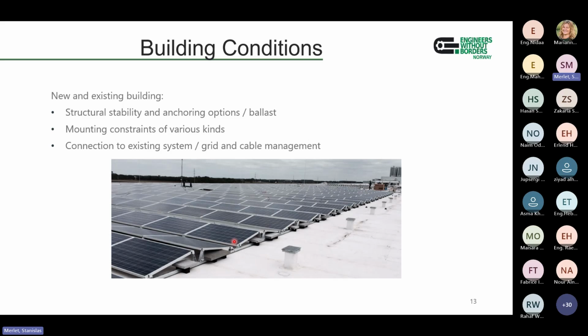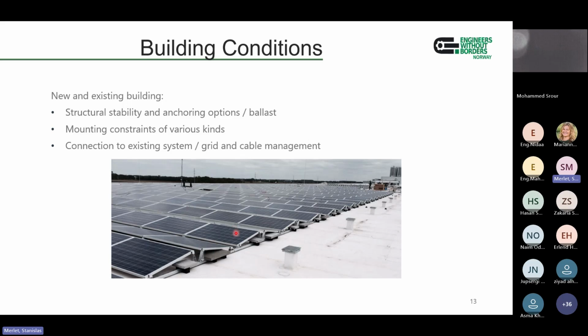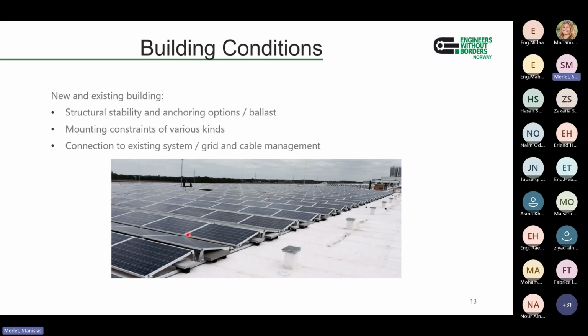I don't know if you remember, but the module is divided in 3 usually. So that's just a shading assessment, and it also applies for the dust. When the dust accumulates, you usually have a small ridge in there with the frame of the module, and the dust might accumulate just at the lowest part of the module, and then all cells of these lines will be shaded and then not producing. But if it's mounted this way, then only one diode of the 3 will be impacted. So that's a better yield at the end.